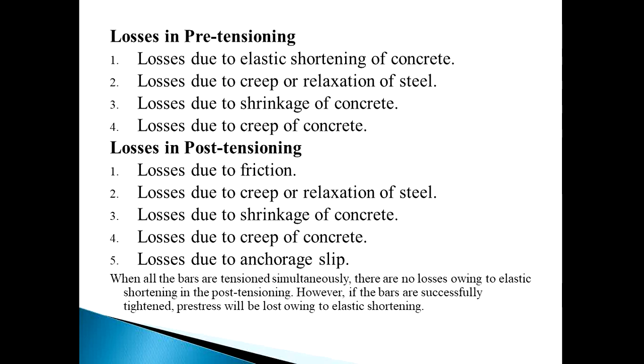First of all we discuss losses in pre-tensioning. The first loss in pre-tensioning is the loss due to elastic shortening of the concrete. Second one is losses due to creep or relaxation of steel. Third one, losses due to shrinkage of the concrete. And fourth one is losses due to creep of the concrete. These four losses are considered in pre-tensioned concrete.